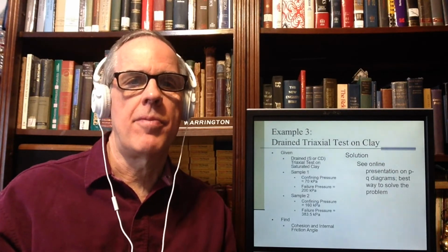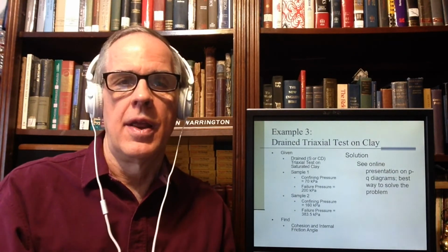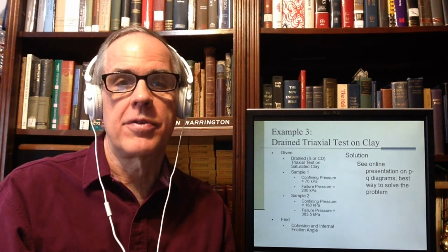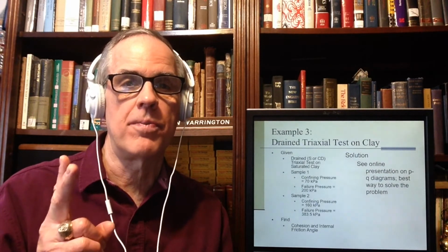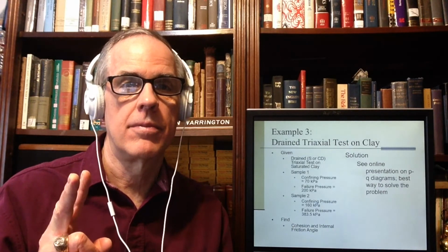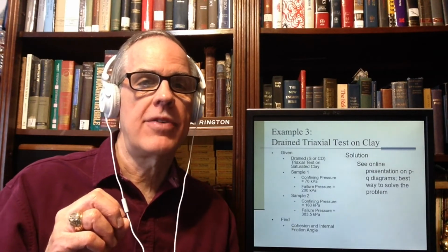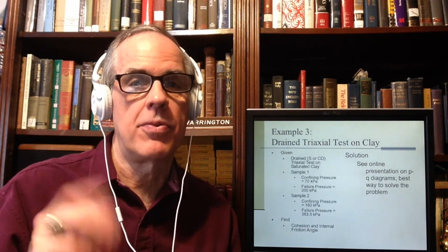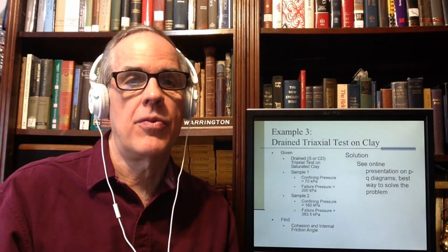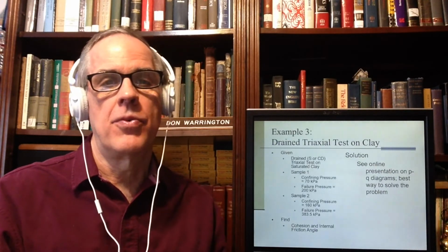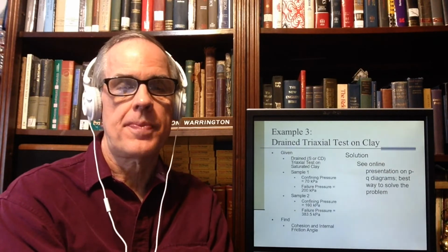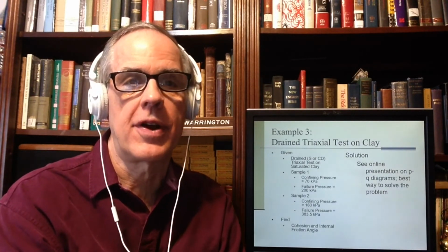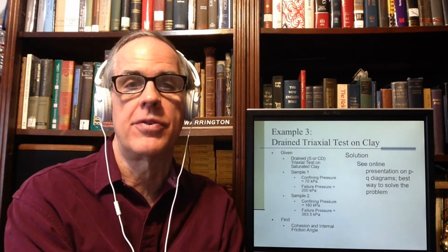They're hard to do. I mean, you can draw some circle and whatnot, and with CAD you can get exact results. The other trouble with Mohr's circles is this: this one only has 2 data points. In many cases with a triaxial test you run 3 data points. Now, 1 or 2 things is going to happen. One of them is that you're going to notice nonlinearities. We talked about that with the pre-consolidation stresses.